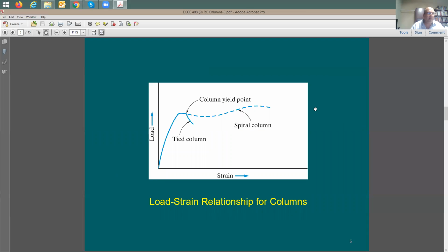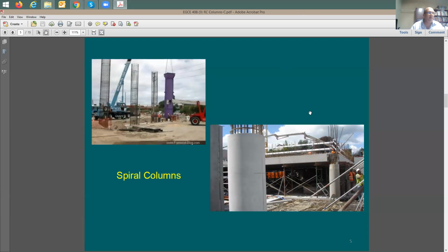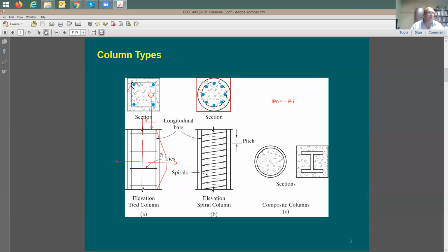of the concrete. Confinement means that when you provide this containment for the concrete with the ties, and then you start with pressure, it wants to open up. But what's going to stop it is going to be all of these ties. So these ties here are going to improve the properties, including the strength and the ultimate strain of the concrete. And we're going to see a diagram for this in the next slide set. So having the ties is going to help to reduce the buckling length for the vertical rebars exposed to compression, and also is going to help to increase the properties of the concrete.